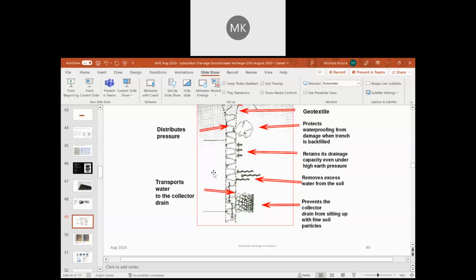No, it just shows the health factor only. The same way, mass per unit area is the health of the geosynthetic and will come into the picture, but not more than that. Performance is related to other factors, but still weight is one of the factors. So mass per unit area should be greater than or equal to 410 GSM.